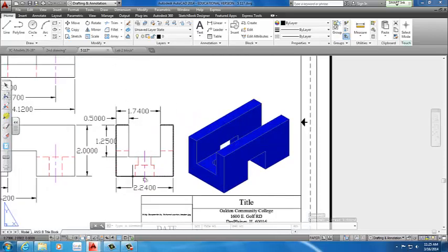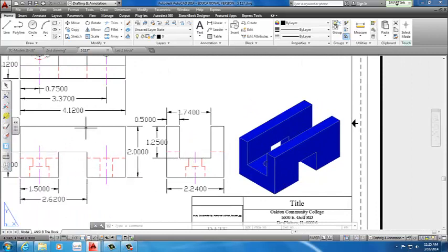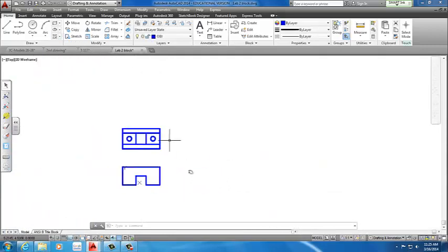So we're going to design this part right here. Basically, it's 2.24 across, and the height is 2 inches from the top of the front view. Now, at this point, you can put the annotation basically, the specified sizing, again, as a reference line to help you.